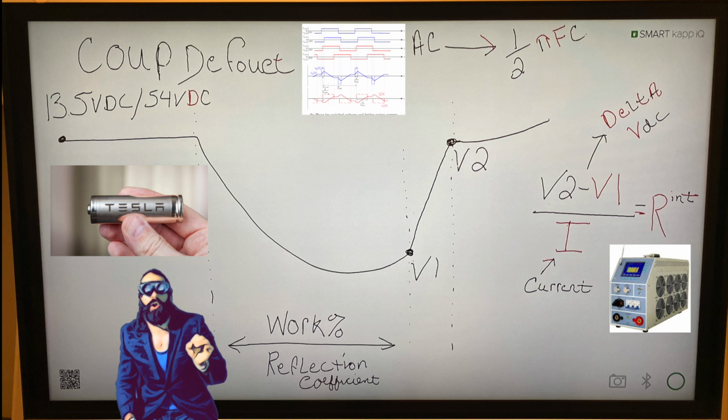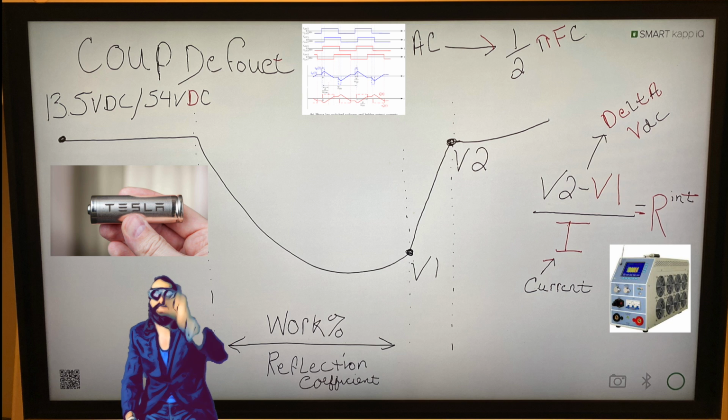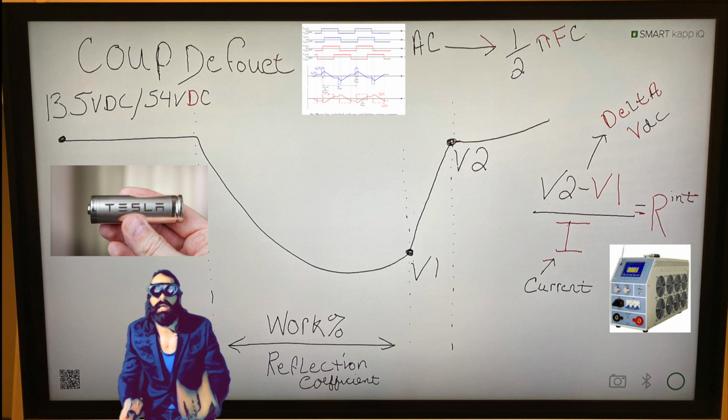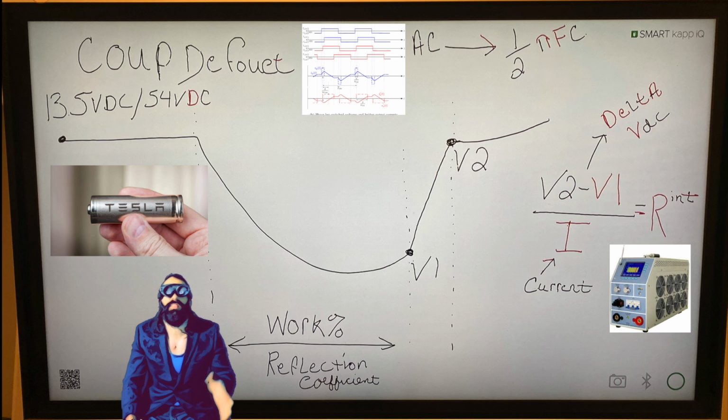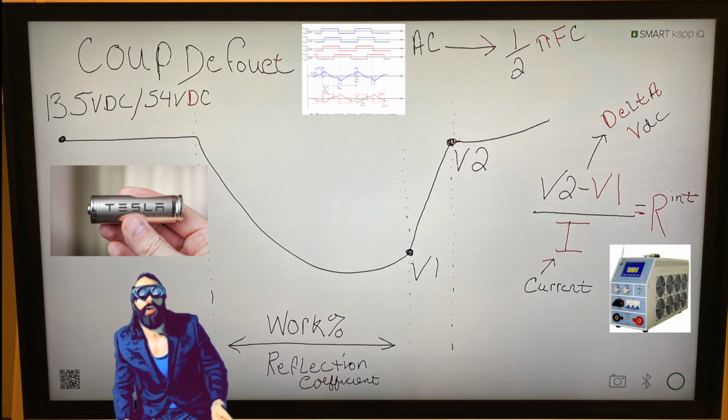So I find this all the time when I go out to different facilities, is that this same system here, depending on how the rectifier and the charger is set up, because it's constantly jumping, right? So when you take this measurement here and here, the charger is trying to equalize the DC bus. So if you're testing in load groups of load 1, load 2, load step 3, load step 4, this can jump around quite a bit. It can cause it to become erratic. So ask your vendors, your battery monitoring manufacturers, if they are utilizing an averaging algorithm. And if they say no, or yes, ask them to elaborate, because this system can also degrade batteries in a DC current